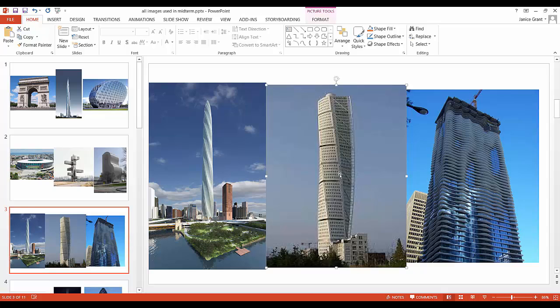This one also, you can use the blend tool, which is sort of like the loft in AutoCAD. Very similar. You create on different levels or reference planes your box or that shape, and then like this one would be different over here, and then rotate that geometry so that the tower rotates with that geometry rotation.